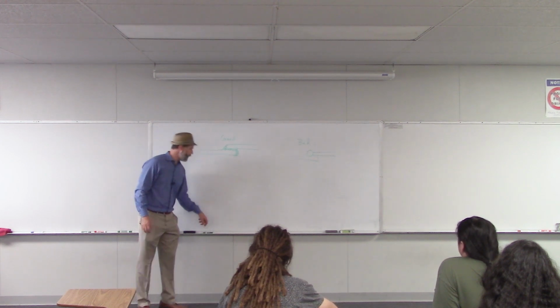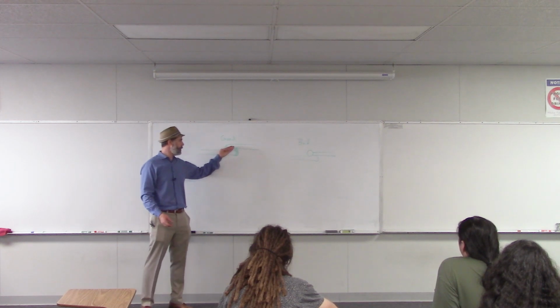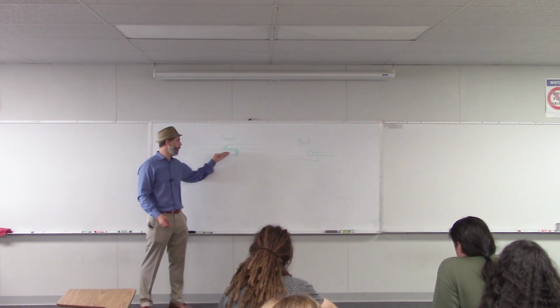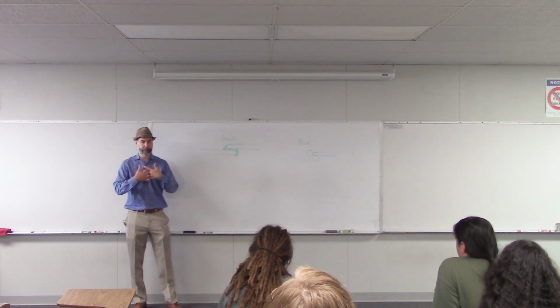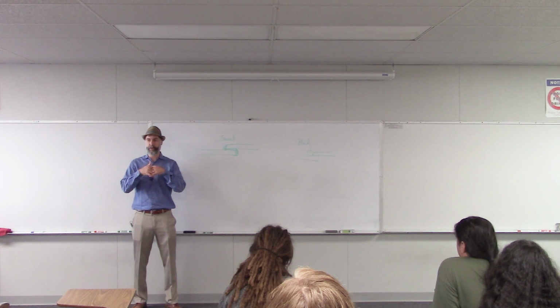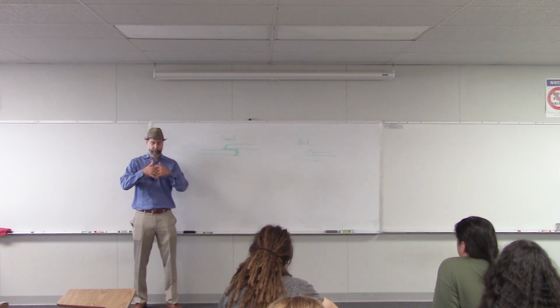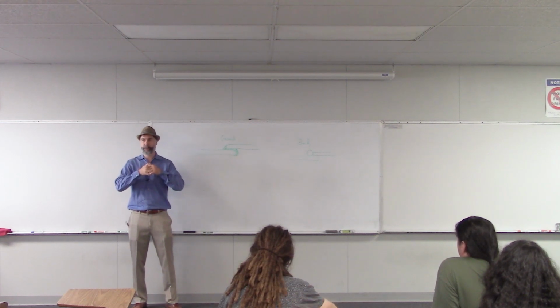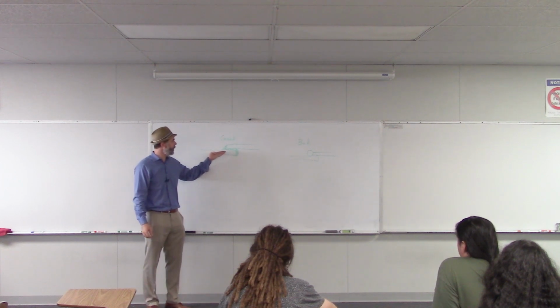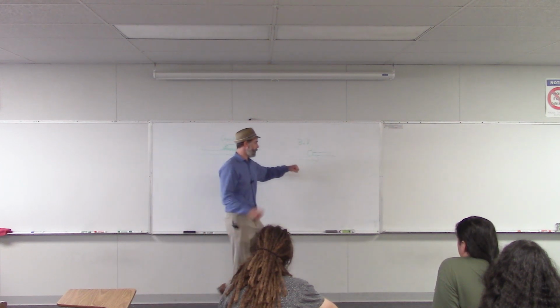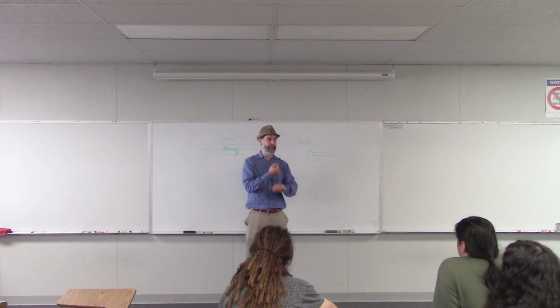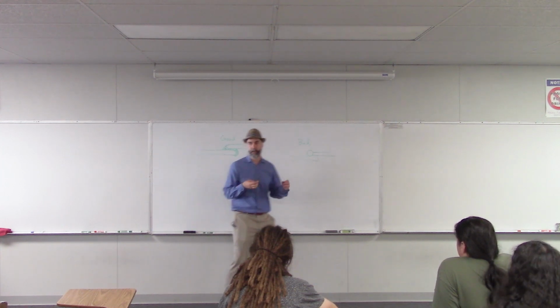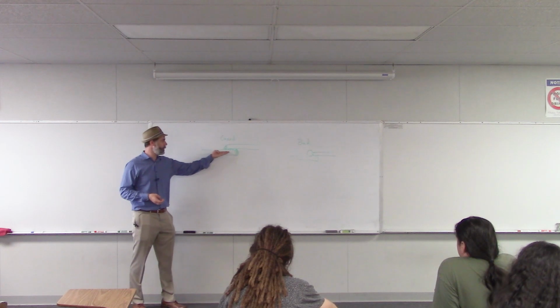And what's more, really what you want is for the outside metal on your components to actually melt and sort of mix in with the melted solder a little bit. That's called an intermolecular bond, where these two different types of metals actually mix a little bit. That's what you're looking for. That's a really good, strong solder joint. Whereas over here, you just have kind of one thing sitting on top of something else, and it's likely to break. Okay, so really, this is our goal.